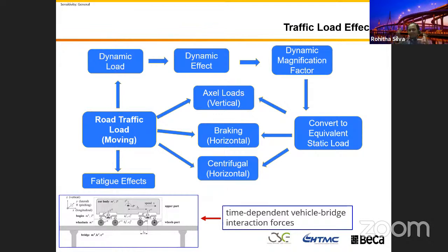When you are designing for traffic, you can have 100 PhDs, but still you can't come up with the conclusion. The bridge and vehicle interaction behavior, you can't conclude that one, because if you come up with a solution for one single span, it's going to be totally different for the next span, because when you build the bridge, creep, shrinkage, all this behavior, your bridge deck will be different. Because of that, there are a lot of uncertainties to get the right numerical model or the answers.